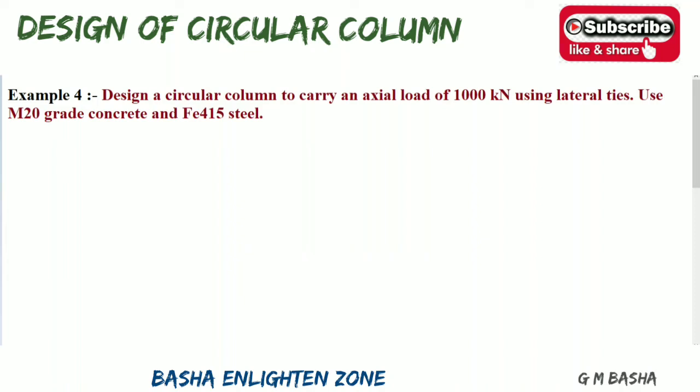In this lecture, I would like to explain another example based on the circular column. See here in the question: design a circular column to carry an axial load of 1000 kilonewton using lateral ties. Use M20 grade concrete and Fe415 steel.